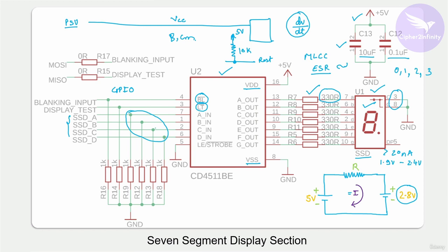So you have to make sure that these pins are connected to the ground by default, so that in this kind of situation, these different numbers should not display on the 7-segment display. So when you connect the pull down resistors on these pins, it ensures logic 0 on all these pins, and as a result, you are just going to get 0 on this 7-segment display. That's basically the purpose of this pull down resistor.